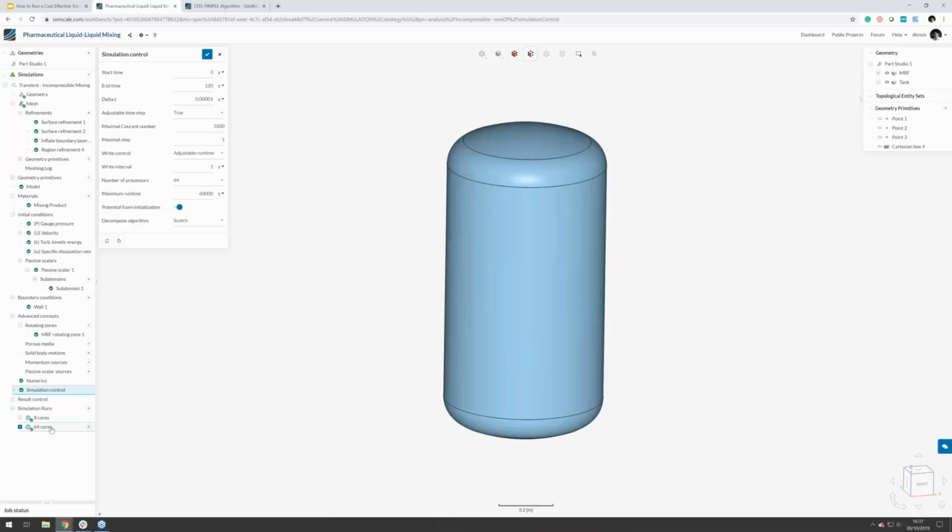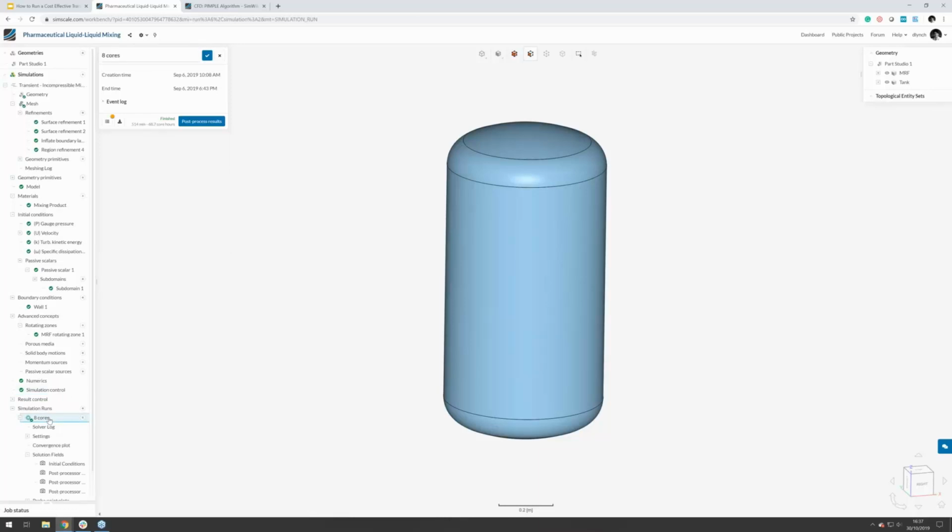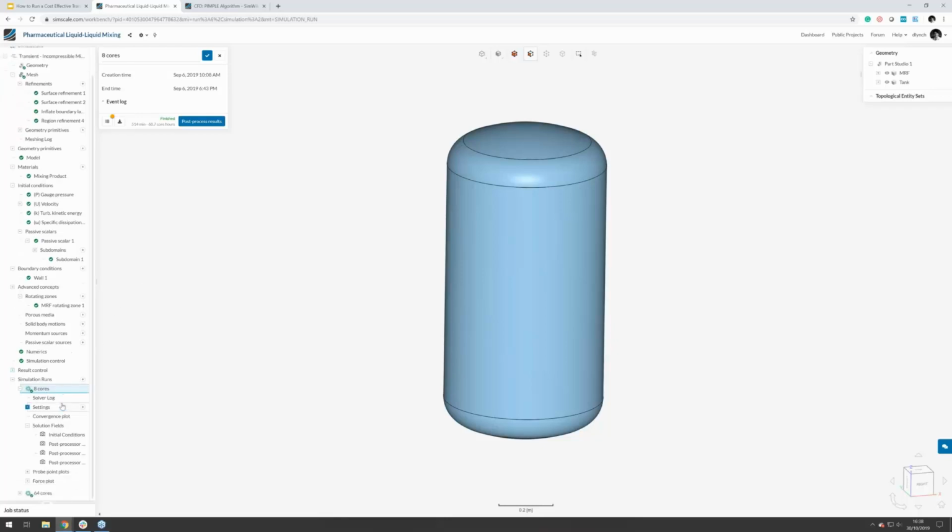So typically on SimScale, 8 cores is what I would recommend, up to about 1 million cells. You would only really need to go to 64 cores or 96 cores if you had 30 million cells or 50 million cells, and anything in between. So the idea is not to just pick the biggest amount available to you, but instead put a sensible value on that. And the reason for that is because if you look at the core hour usage for the 8-core version, you can see that it's used 68.7 core hours, running it for 500 minutes.